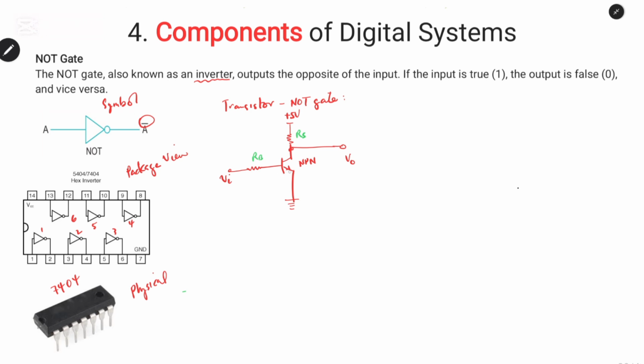We only care about a huge amount of current flowing from the collector to the emitter. So the current from collector to emitter can be large, and from the base we only need a small amount of current to switch on this transistor. Therefore, we have the base resistor connected from most of our circuit.